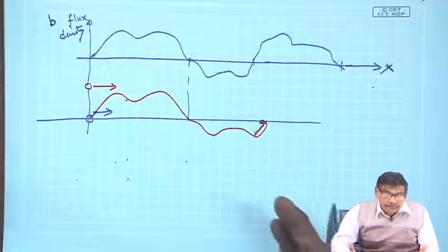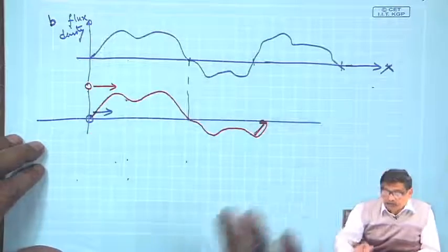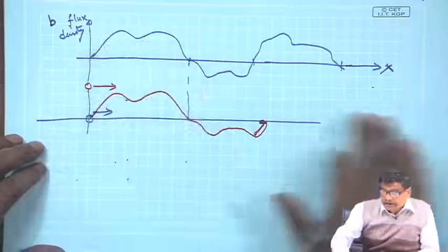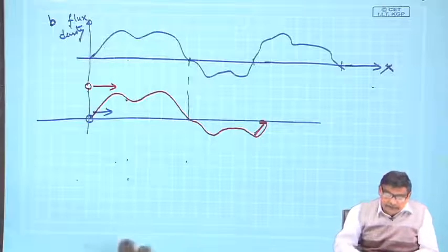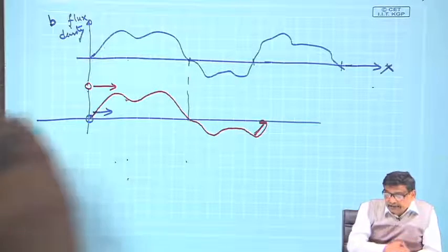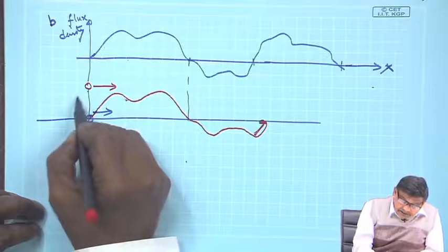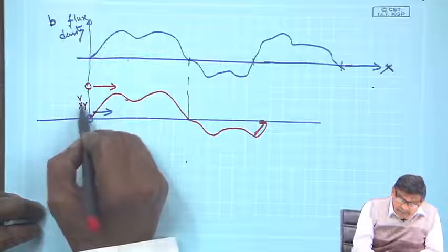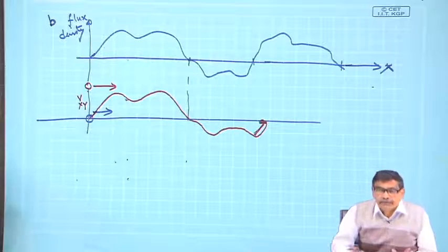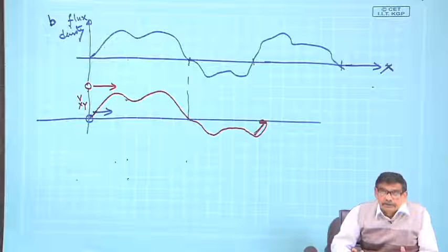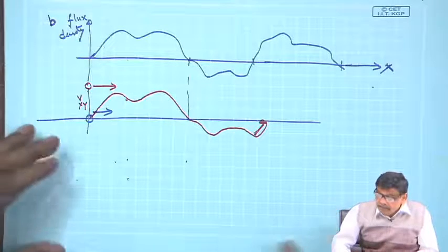Therefore, if you have a spatial description of B along space axis, and through that axis some conductor is moving, the EMF generated, V x y, will be identical in shape to that of B, BLV, LV are constant. So, that is the idea.